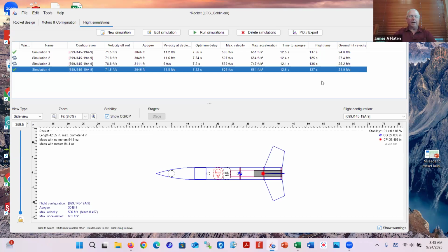So this is a look at an existing model, fiddling around, adding a couple components that weren't there, adjusting the components that are there to be more appropriate in material, in surface finish, in length, in weight, and in actuality. If it turns out that I have the parts in front of me and have weighed them all, I could go back and I could say, oh, by the way, that nose cone really is 5 ounces or 7 ounces. It's not 11 ounces as the model currently has. But this is good enough for a start. And you can continue developing it, evolving it, polishing it, making it more and more effective as you go.